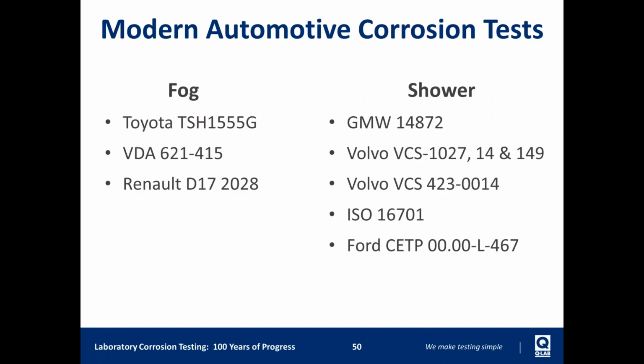So when we say modern automotive corrosion tests, these are the ones that we're talking about, generally speaking. You'll notice that most of these are automotive OEMs. They're the ones that have really been driving this technology. There's not as many corrosion tests that you'll see like this in the different standards bodies like ASTM and ISO, just because those are more open, and a lot of times it's a metallurgical task group, whereas the automotive manufacturers are the ones that are really pushing this salt delivery and controlled relative humidity.